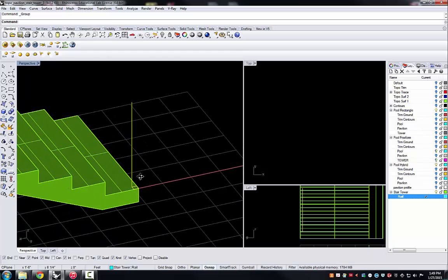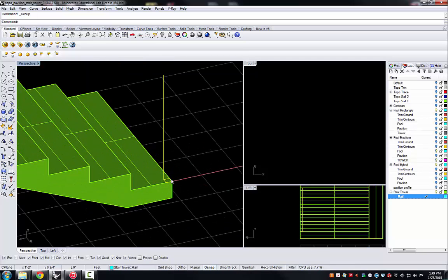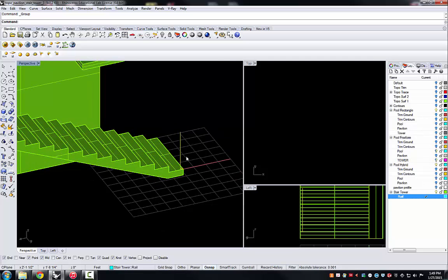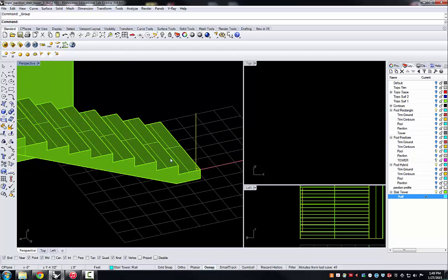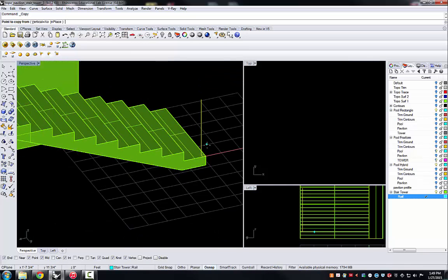And I'm going to use this now to copy this vertical dimension with an offset from the stair tread and the edge of the stair to various locations, and I'll have to rotate it and whatnot. But this is useful rather than working off of the very corner of the stair, where when I create a circular pipe around this geometry, it would overhang the stair. I've offset it inward. So now I'm going to take this and I'm going to copy it multiple times.